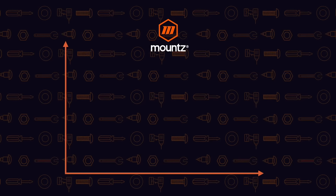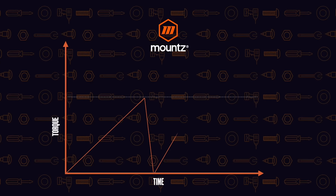And so if we looked at this on the graph, we could come up, we would reach our torque value, the cam was reset, we could run it back up again, the cam will then again reset, and we can do that as many times as we'd like, but we can never apply more torque than what is going to be allowed by that cam mechanism.